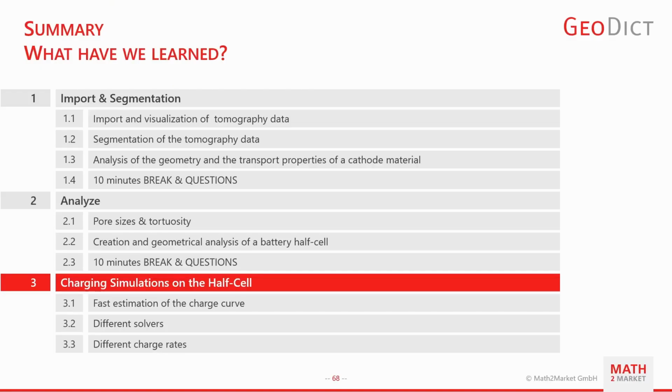We now finished the workshop, and I want to summarize what you've learned during the last 1.5 hours. You learned how to make an import and segmentation of micro CT data or FIB-SEM data. You learned how to analyze the geometry to calculate the transport properties and the cathode material. You learned 2 methods to calculate the pore sizes. And you know how to calculate tortuosity.